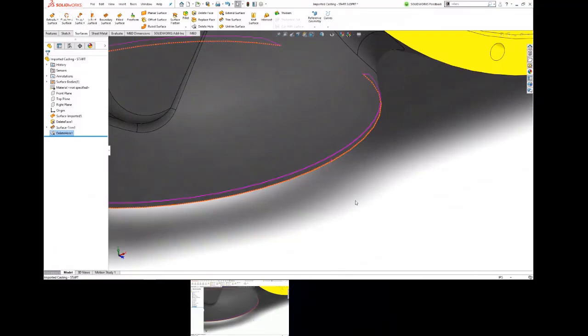Other options that were boundary surface, or what was the one you're suggesting? Fill is your best go-to when it's not a straightforward four-sided patch. Okay, fill is kind of a subset of boundary surface, is that right? Fill is a little more general purpose because it works on any sided. Boundary surface is four-sided patch. But when you can, try to get to four-sided patches.